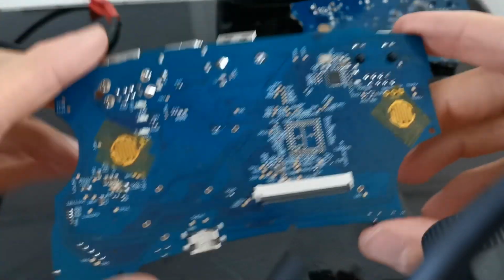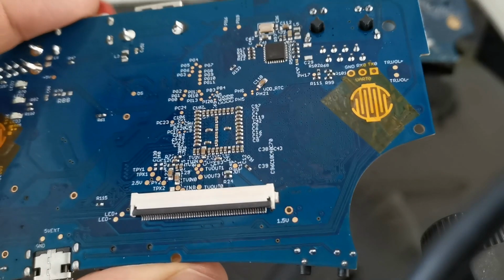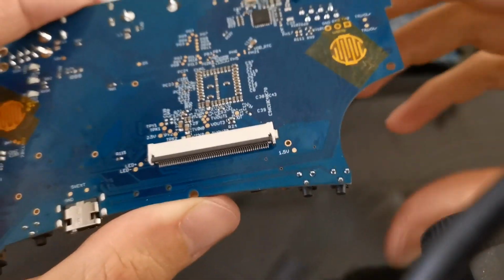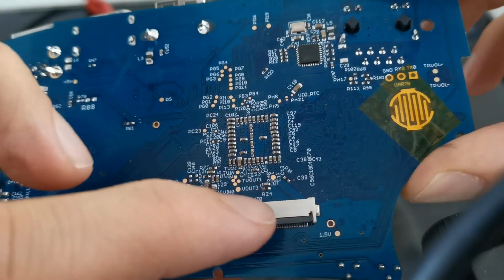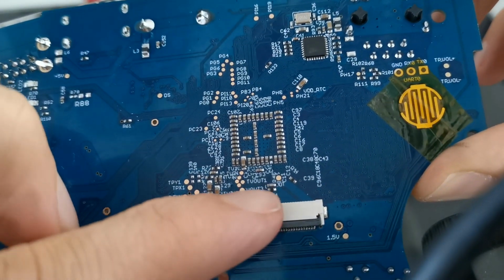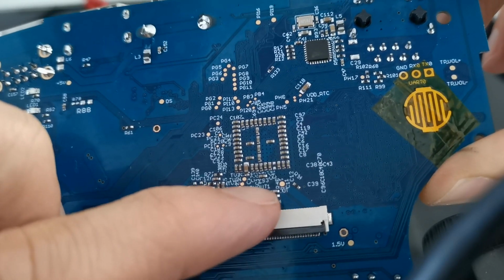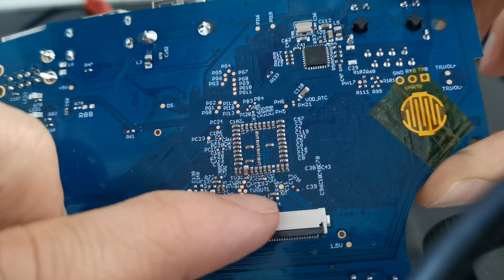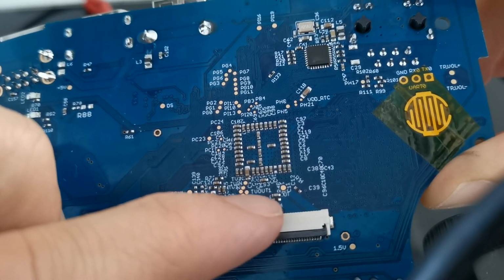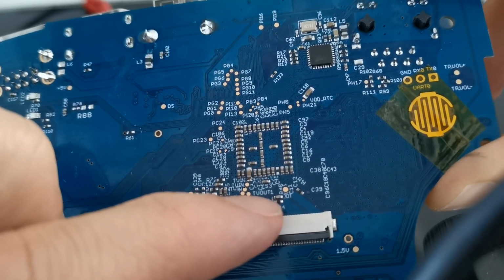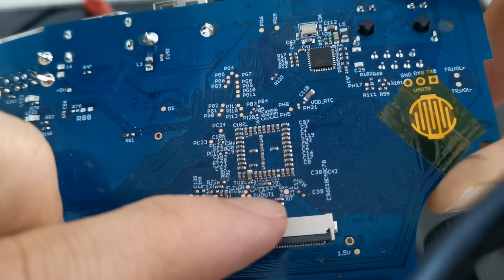Now we are going to need to do something more complicated. We discovered on the first test that we made an error on the assembly. You see those two small components here, the one just above R24 and the one above? Well, they are actually reversed, so the LCD does not work this way. So we have to unsolder those two small components and then replace them with each other.